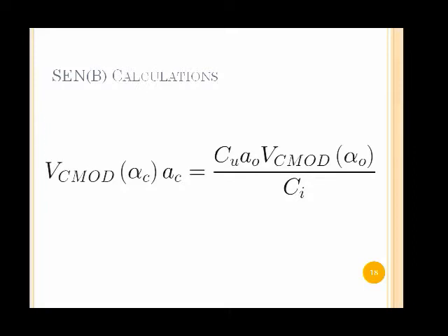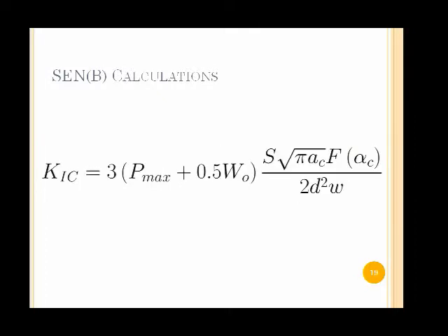So we can just iterate until we find essentially that critical crack extension that gives us the same thing on the right-hand side. And when we do that, we now have a critical crack extension, and we can plug into this semi-complicated looking K function here, which accounts for the peak load of the specimen or the applied stress. It gets converted into a stress over there.